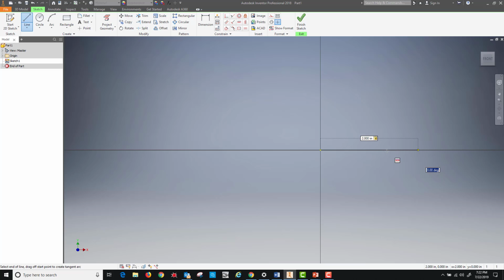If we bring it down right with the line, it'll show you a coincident constraint. That should actually show you the parallel constraint down below, or the horizon constraint, depending upon where you're at. So we've got the constraint showing up down below, the horizontal line constraint, because we don't have any other lines there yet. So if we go ahead and left click, it will automatically make that.